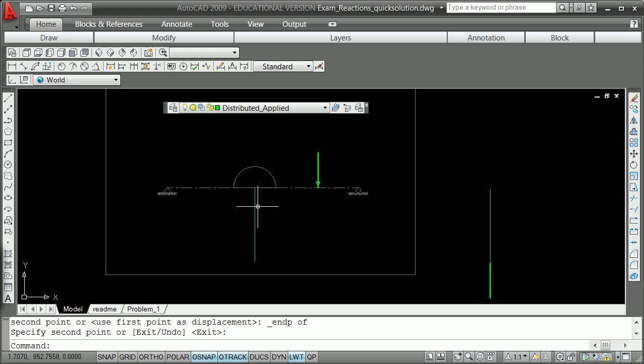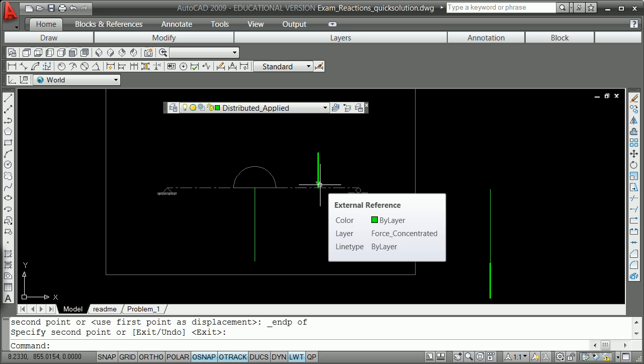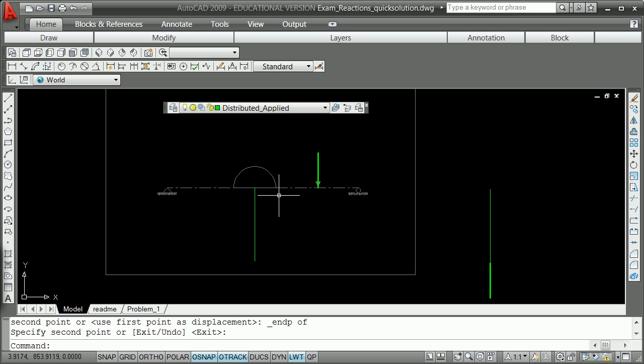What you could do is take out your calculator and do the calculation of this force times distance divided by the sum of these forces, which will get you the distance to the reaction. I'm going to point out this problem cannot be done by the three concurrent force rule, because these forces are not concurrent. You do this by what?